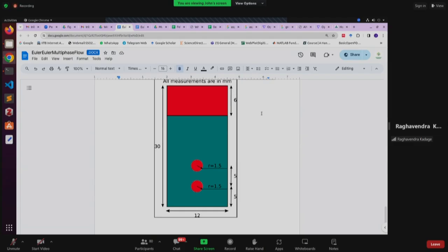Yeah, and also the residual files that were provided to you will also work. The only thing is, in the residual file, you have to mention which variables' residuals you want to monitor. Say in the case where I demonstrated the addition of a scalar, the same residual file will work, but you have to mention the scalars.